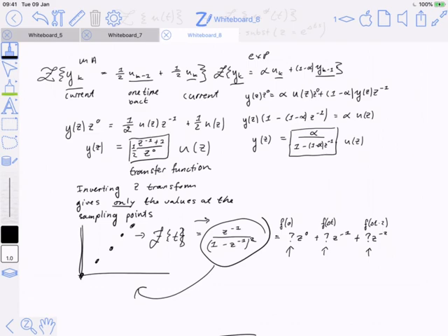Furthermore, I expect you to have this nuanced view that inverting the Z transform is fundamentally different from inverting the Laplace transform, right? Laplace transforms go both ways. If I give you a function of time, you can get a Laplace transform. I can take that Laplace transform, give it to somebody else in the class, and they will get back the same function of time.